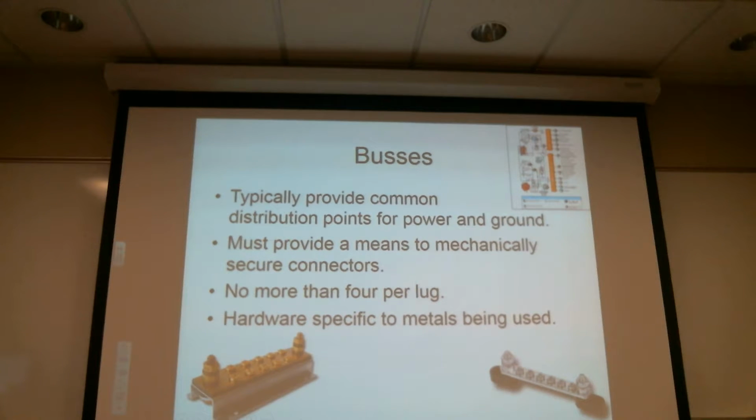The other thing they have discovered is if you mix all these metals up and then run electricity through them, they might corrode. Well, that's kind of logical, right? And depending on the different metals you mix together. I will tell you, stainless steel is sort of remarkable. For being stainless and not wanting to corrode, you get it near copper, bad things happen. For the copper, you get near aluminum, really bad things happen to aluminum. So it's very, very bad for other metals.